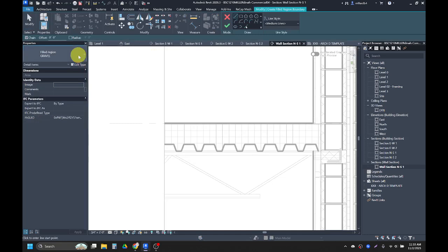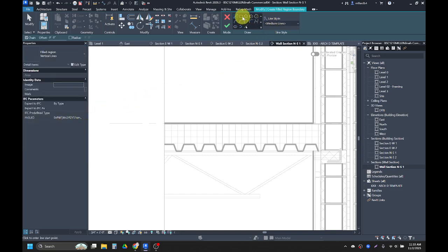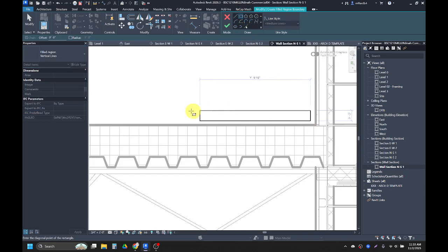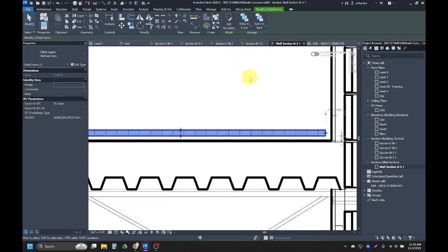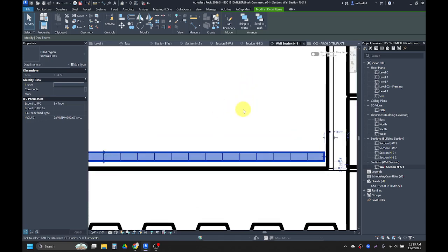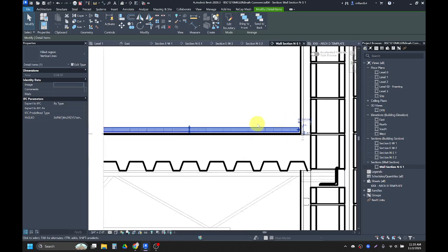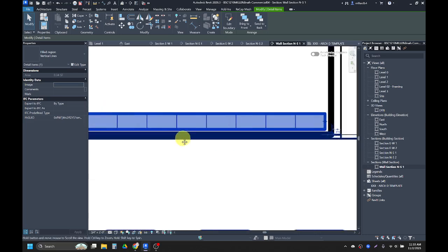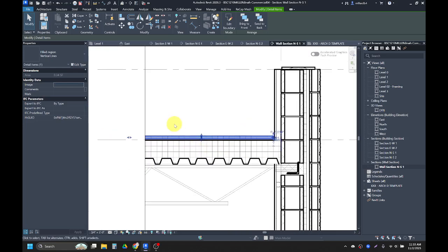This one will be vertical lines with a medium line style, and I'm going to make a rectangle. I'm going to make it 1 inch tall. And again, as long as it goes past my crop region on the left, I'm happy. I'll hit my green check. I'm just going to scooch it over and down so it's not quite exactly flush, but it's pretty close. The more you zoom in, the smaller the amounts, those arrow keys will scooch things up and down for you.